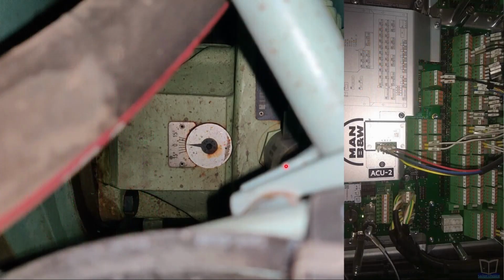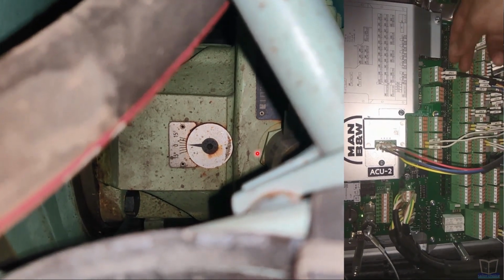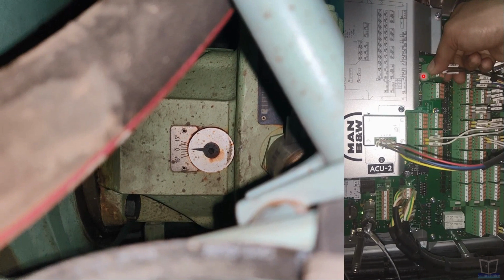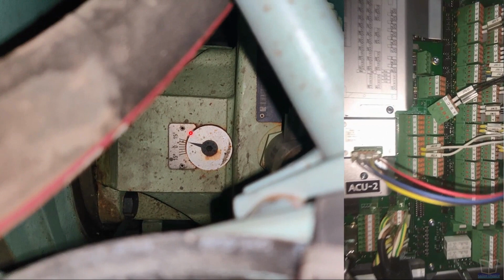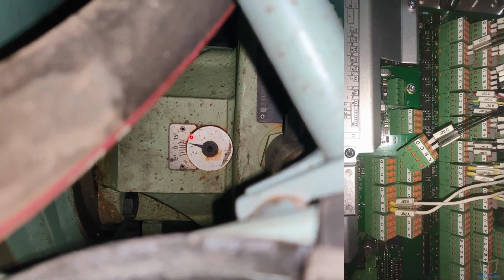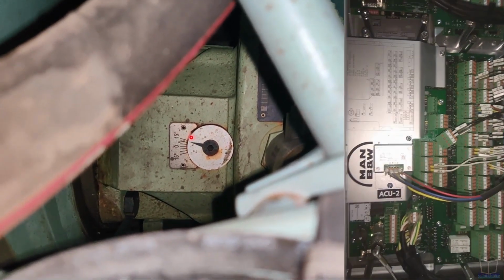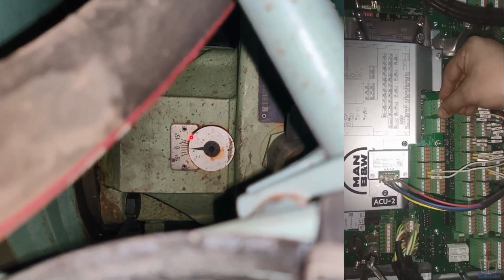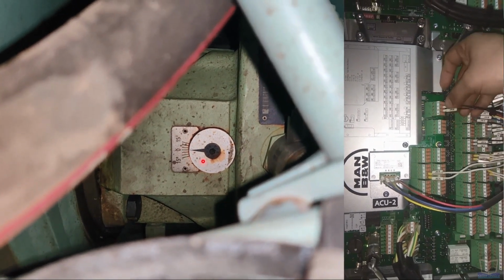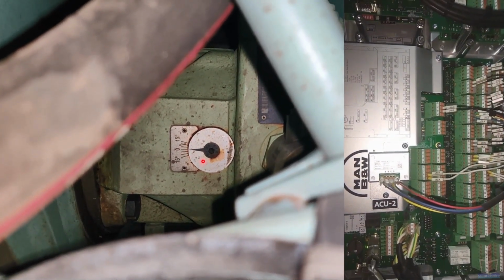So now I am showing you one small video by which you can see practically how it happens. So let's have a look. Now I am going to pull out channel number 20. See, it has moved to its maximum position in ahead direction. Now as soon as I give feedback, it comes to this 0 position. This is how the engine driven swash plate pump works.